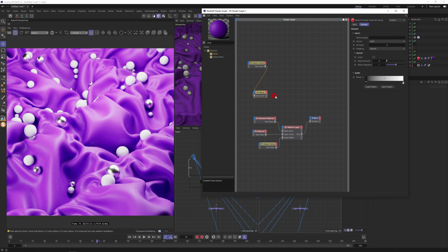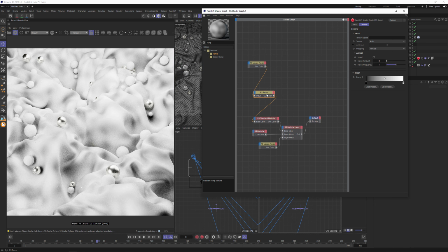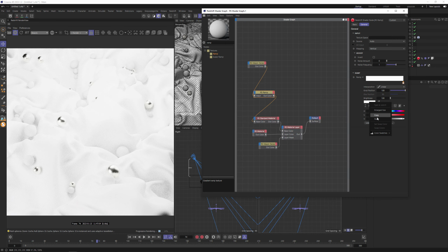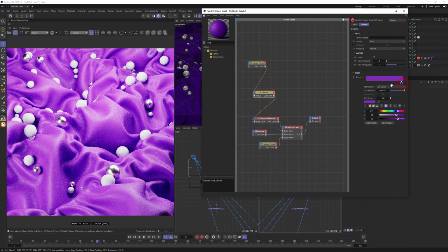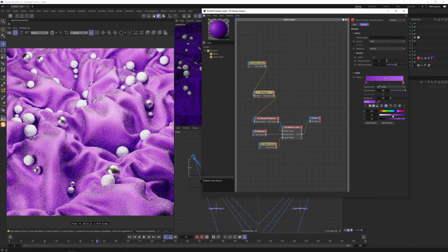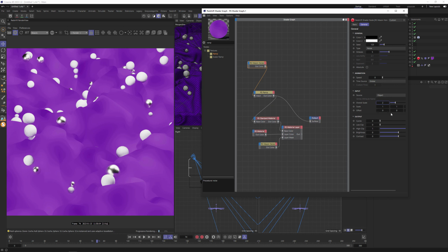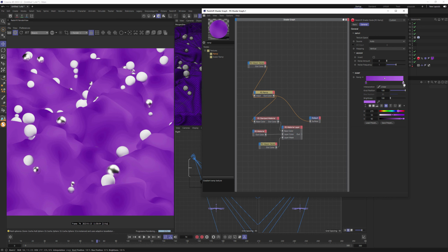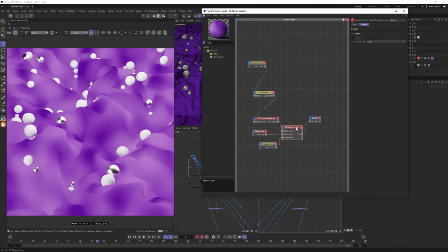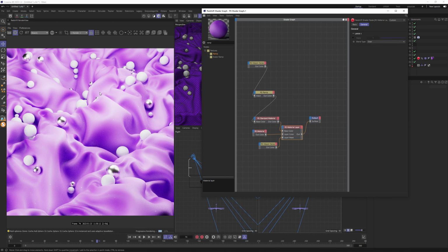I create an RS Ramp, connect it to input, and in base color, so we have black and white gradation of color. Instead of our markers, I delete them and paste our purple one. It should be the dark one, and the right would be a bright one. Connect RS Ramp direct to output and play with scale, maybe contrast, to have a little bit of difference in the diffuse albedo shader, adjusting the difference in color and check how it looks in RS material directly.